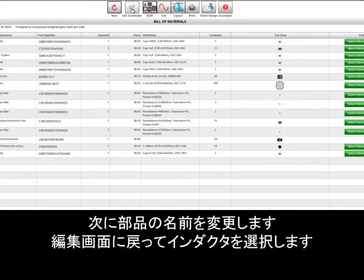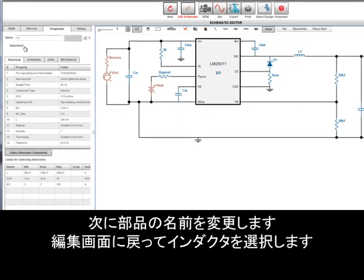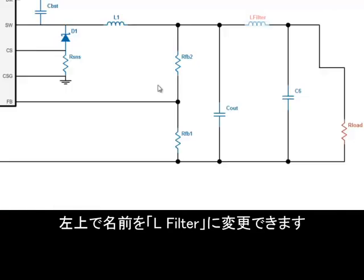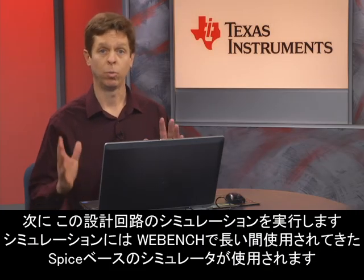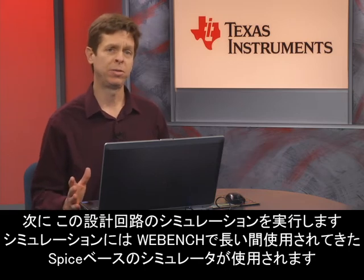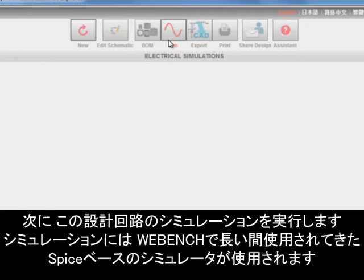Now, I want to change the name of these components, and so I'll just go back to the edit screen and select the inductor. On the upper left, I can change the name to L filter. And now I've just customized my schematic by adding a filter to it. So now what you want to do is run the simulation of this new design, and that uses that same SPICE-based simulator that you've enjoyed in WEBENCH for so long.